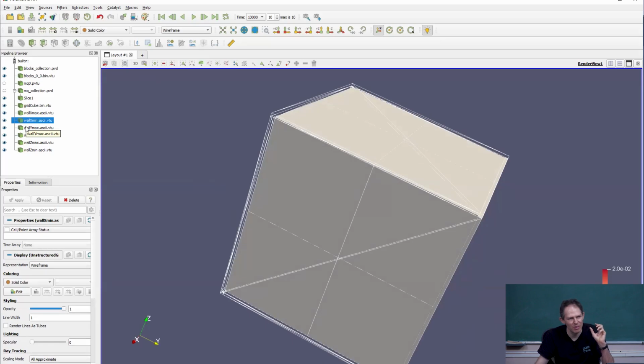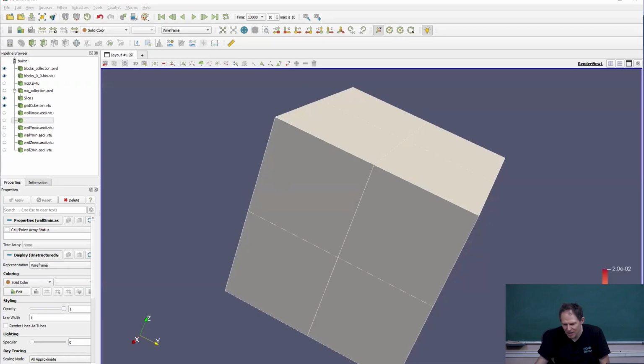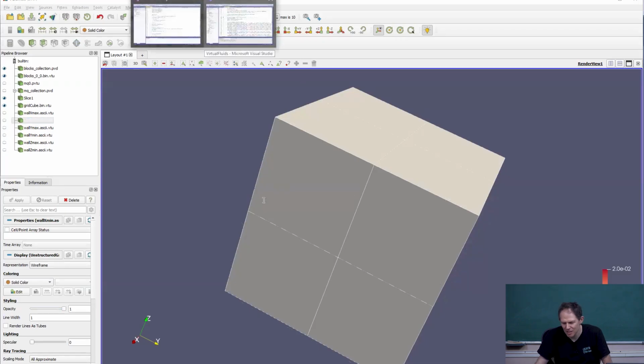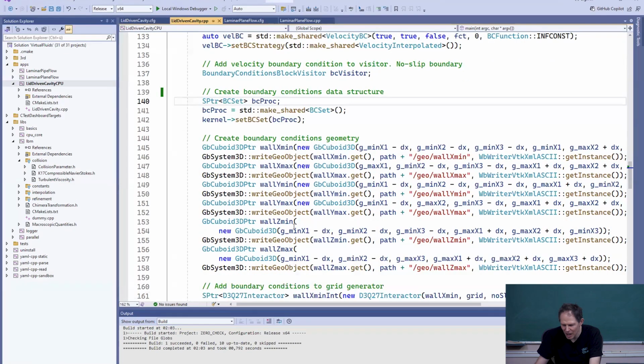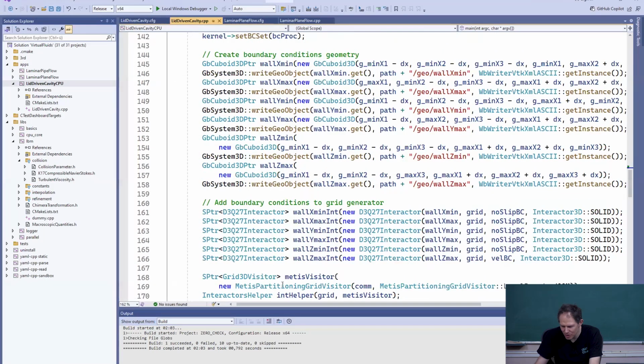a little overlap with the grid, and where they overlap with the grid, the boundary will be generated, and automatically by the grid generation, the subgrid distance will be identified such that the interpolation can also take place. Yeah, so they are put now all around, and obviously you have to generate them for all the 6 different directions, and we also write them out.